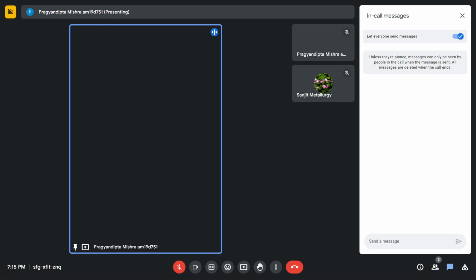Similarly, we can write these two also. So if I substitute and solve, your change in volume will be equal to (1 minus 2 mu) divided by E times (sigma x plus sigma y plus sigma z), if you substitute and solve, right?